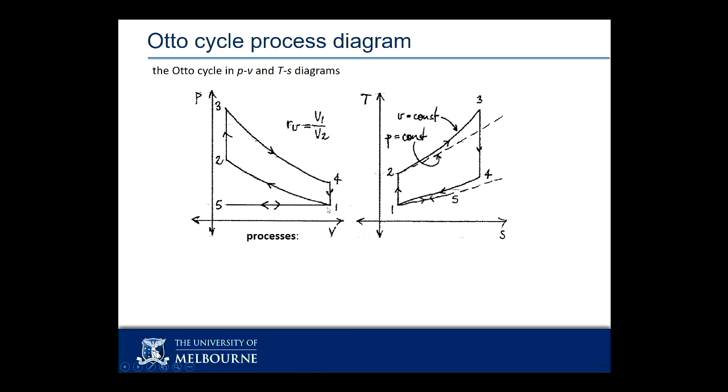So the piston travels its whole volume from bottom dead center to top dead center during the exhaust and intake process. So it goes push everything out. It's constant pressure because I open up a valve to the outside world. So suddenly everything is at atmospheric pressure, approximately. So at atmospheric pressure, I open up a valve to the outside world, I push all the air out, and I draw in new air, ready to start again. Now this process does basically nothing, and so more often than not we ignore it for the analysis of the Otto cycle.